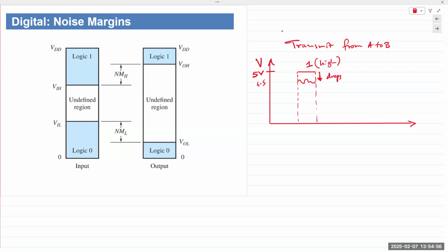So we know which environment our system is going to be used in. So we know what kind of voltage level it could drop to potentially. So we build that tolerance into our system, meaning even if some noise signal arrives and it drops our level down to a certain level, we would still accept that level as logic 1. So if we send 1 from point A at point B, it's still recognized as logic 1. And thus, it is able to reject noise.